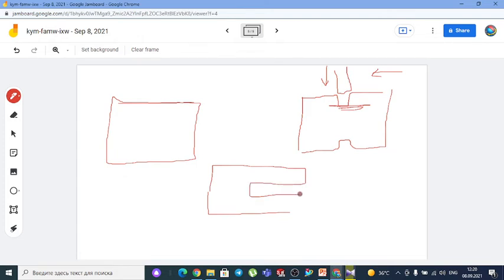For example, if we have a hole here, the tool goes in this direction. There is the holder here, and it enlarges and improves the surface of the existing hole. Then it goes in the reverse direction, in this way.